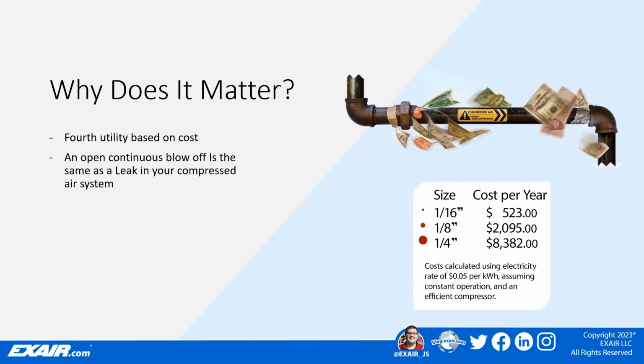If you walk into your facility during a shutdown and you hear blow-offs running, that's equivalent to a leak in your compressed air system. And Compressed Air Challenge tells us even a leak as small as 1/16 of an inch can cost you up to $523 a year.